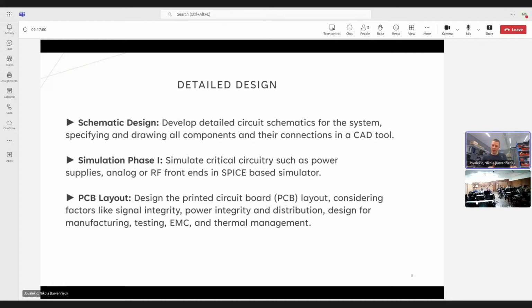So maybe you have produced 10,000 pieces, but maybe 9,950, which is very high yield, will be actually properly assembled. These 50 will not work because there was some error in assembly. For example, imagine that you have a small capacitor, 0402, and when the board assembly was going through the reflow oven, that component finished like this. You know, it was not on the pad. It is called tombstone. It was like this. So it was not soldered.